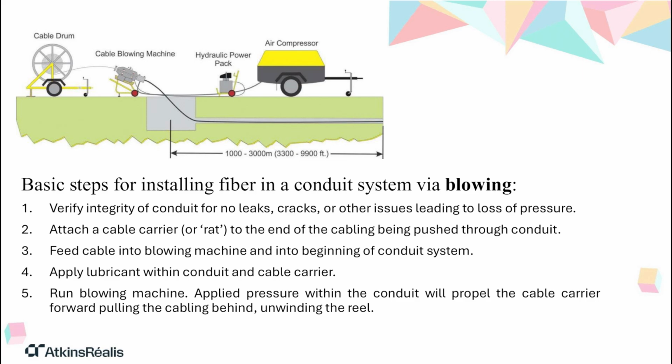Wow, that's a lot of extra cable. And bend radius, too. Always critical. You can't bend fiber too tightly, the signal escapes or the glass breaks. FDOT specification 633 defines the minimum bend radius, often something like 14 times the cable's outer diameter when it's under tension. And one more FDOT rule, no direct burial of fiber. It must be inside a conduit for protection.